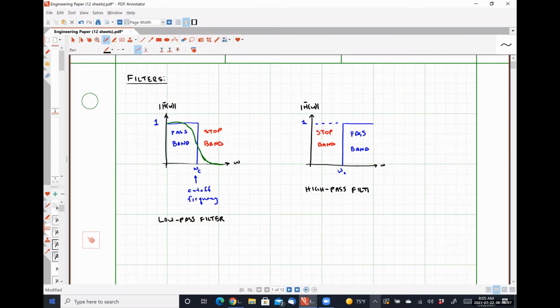So everything above a particular frequency does not get attenuated. Everything below that cutoff frequency does. We'll see that a practical high pass filter has effectively a similar response. It's going to start off low and then increase like so. So there's still an actual range of frequencies it takes for the filtering to occur.